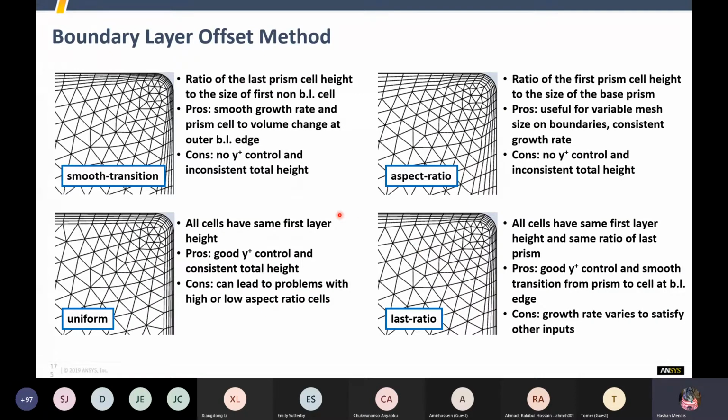The other thing that we want to talk about as well is the boundary layer. Thinking about if you've got high pressure gradients, if you've got a wing that might be separating, or something happening like heat transfer, we want to capture very accurately what's happening at the actual boundary layer. It's a very thin layer, because that gives us a good idea about what the flow physics is going to be. So we've got these prism elements that we're going to be generating.